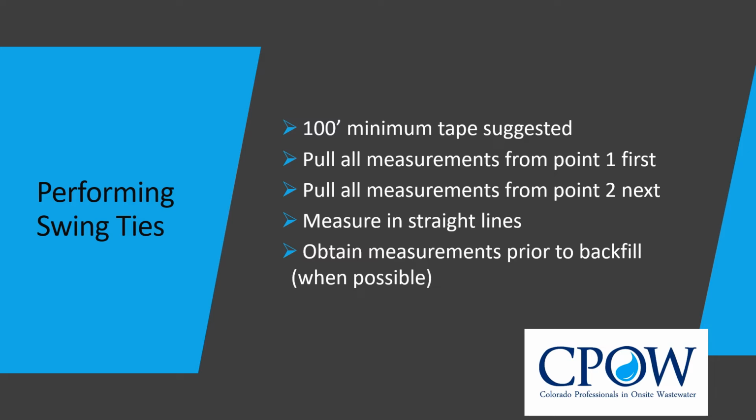Measure in straight lines. Trees can create a problem. Soil piles may make this difficult and cause inaccurate measurements. A third point tie-in may be necessary. When to conduct measurements: after installer has everything installed and still exposed.